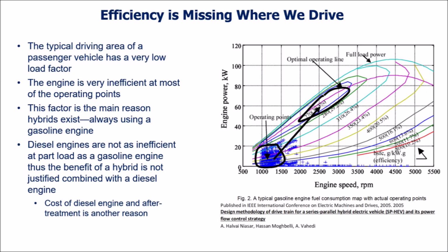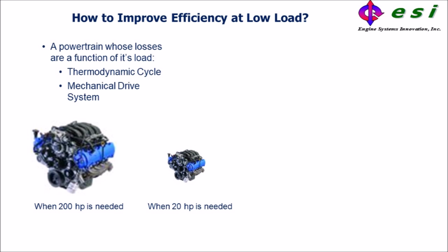To start with, the whole idea behind the CVD is to reduce part load losses. This is because most engines, particularly passenger vehicle engines, run at very low loads most of the time. Whether the fuel is gasoline, natural gas, or diesel, the engines have significantly less efficiency at low and mid loads than at full load. The optimum design would be an engine that always ran at full load, but could change displacement to match the power needed at any moment in time.